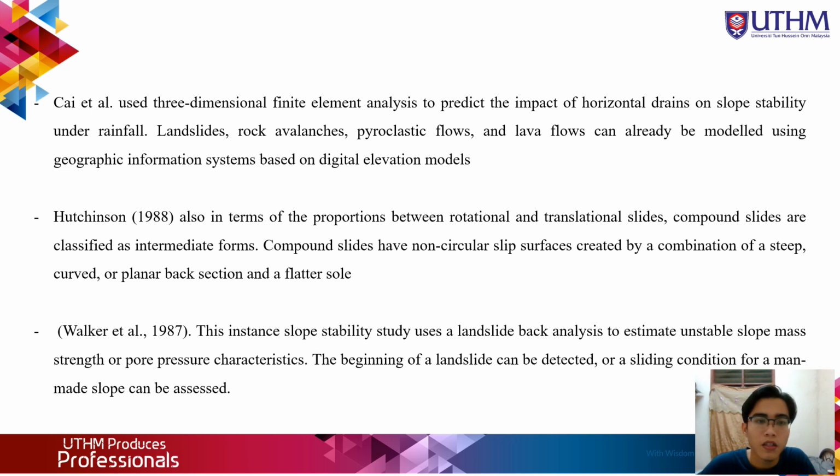Hutchinson, in 1988, also in terms of the proportions between rotational and translational slides, described compound slides, arc-shaped slides, classified as an intermediate form. Compound slides have a non-circular slip surface created by a combination of a steep, curved or planar back section and a flatter sole.